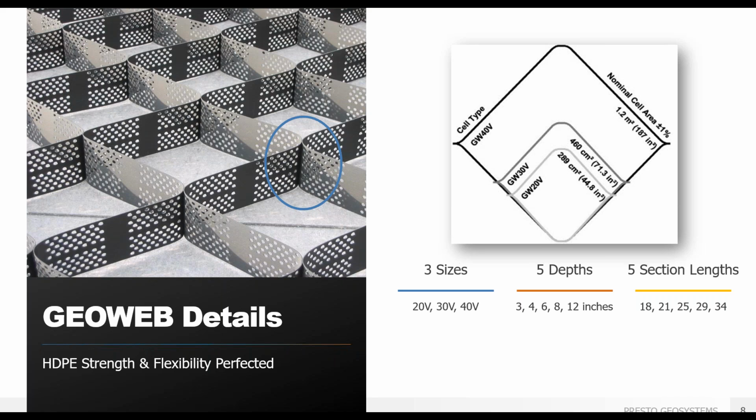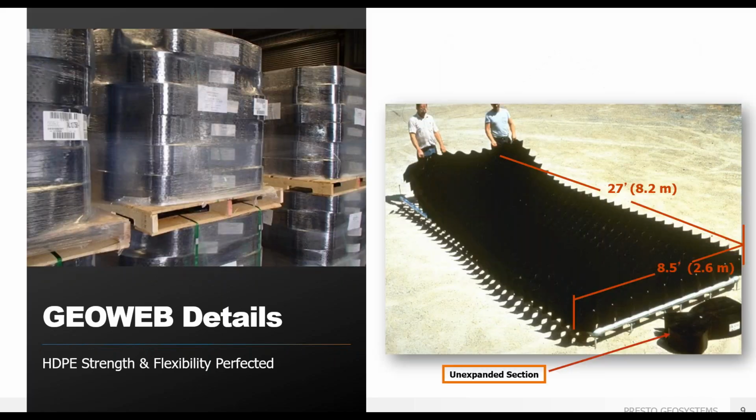So we don't use any fillers or exotic polymer alloys, which can ultimately really reduce the weld strength. And trust me, we've tried all kinds of different blends, even recycled materials. But like I said, 100% HDPE is still the most efficient and longest lasting geocell.